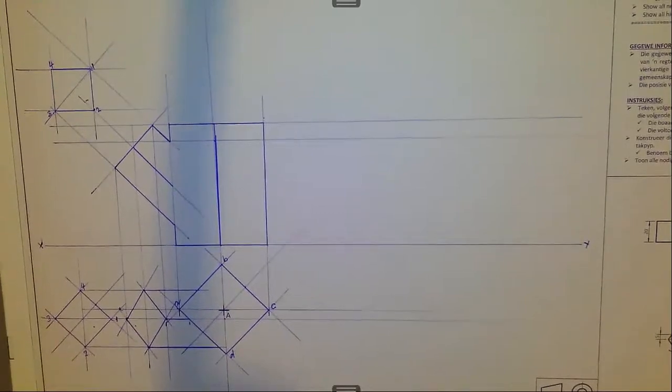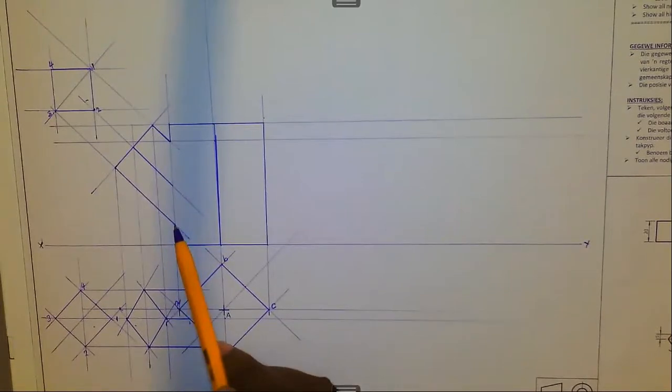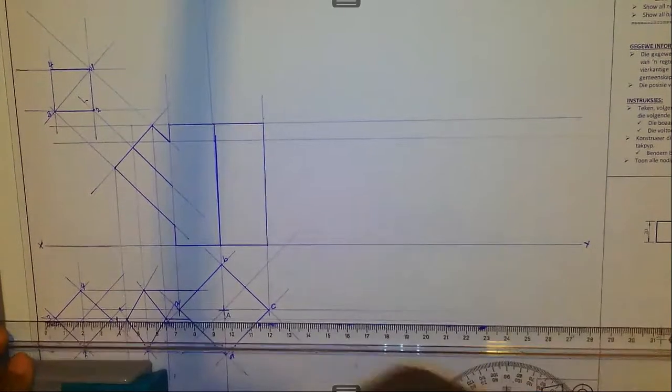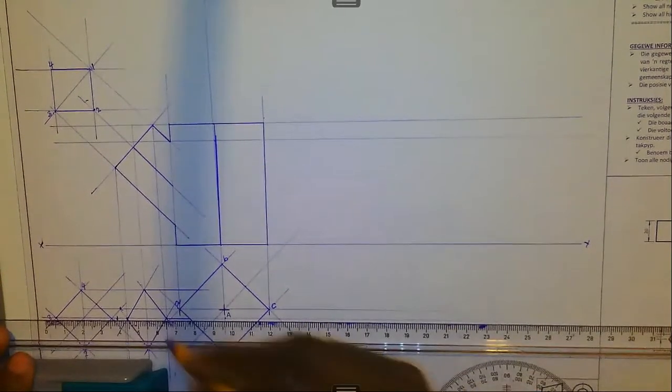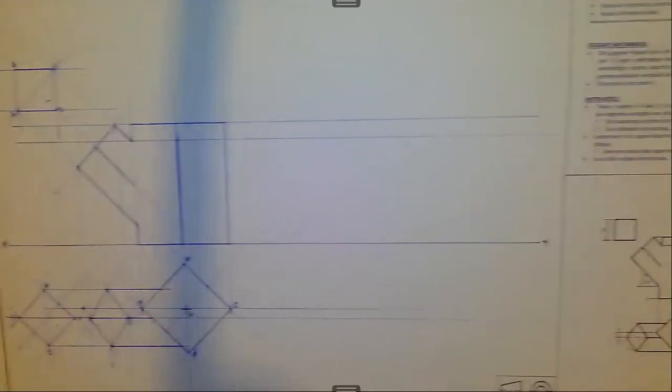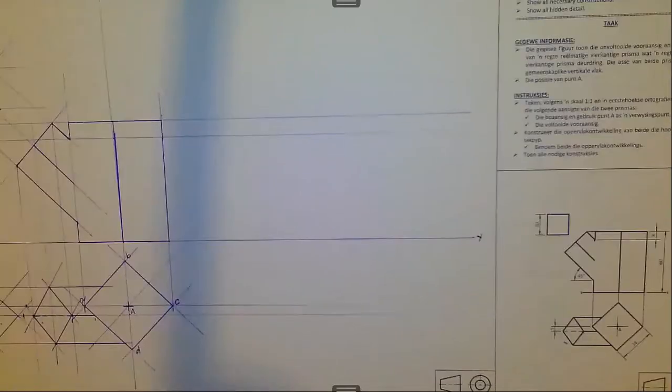Right, so if you are not going to see this edge and you know it is there, you represent that edge by way of a hidden detail. So I'm going to define this one as a hidden detail like that. Right, that way we have now copied the given top view as it is. Right, once we have this information, the next thing now is to come here and now work on completing the front view.